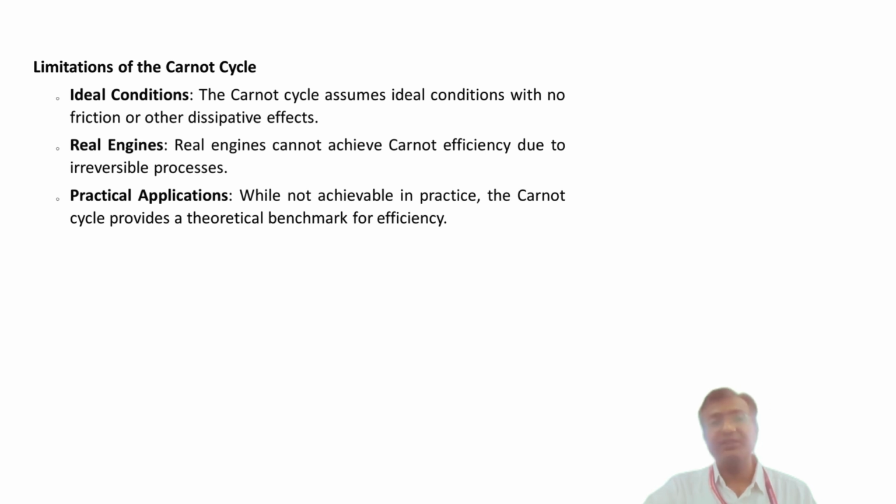Despite these limitations, the Carnot cycle is extremely valuable because it provides a theoretical upper limit for heat engine efficiency. This allows engineers to evaluate how close their designs are to the ideal and to identify areas for improvement. Therefore, the limitations of the Carnot cycle are: first, it assumes reversibility, which is not achievable in practice.